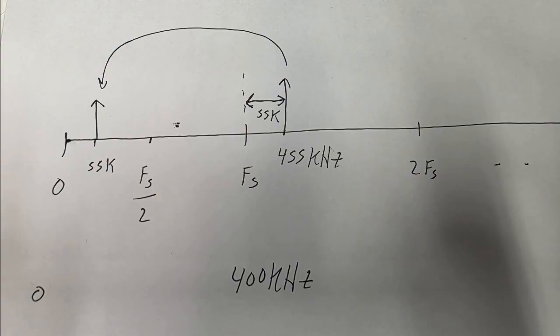So you can see that is why the bandpass filter is needed to ensure that there will be no signal anywhere below 455 kilohertz, because it will also show up in those zones, and we don't want that. So long as we have a bandpass filter in front of this analog to digital converter, we can do this.